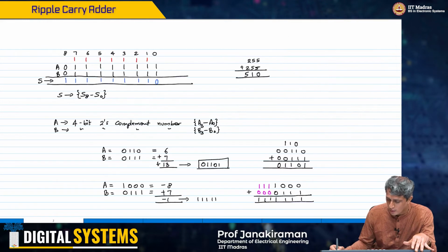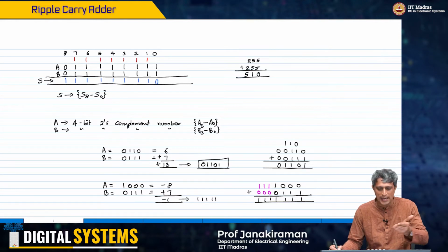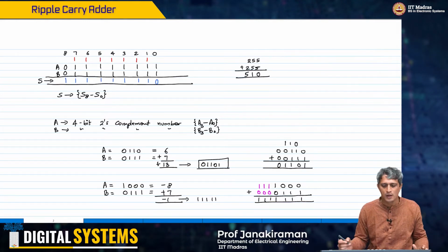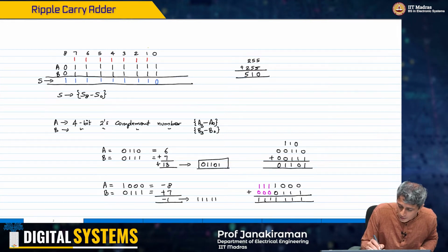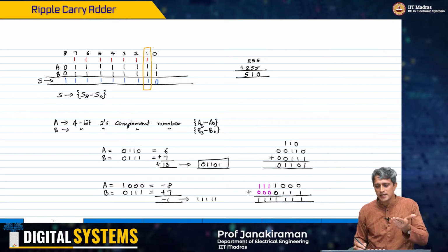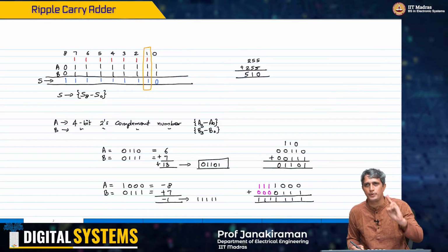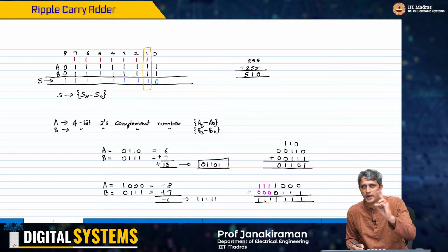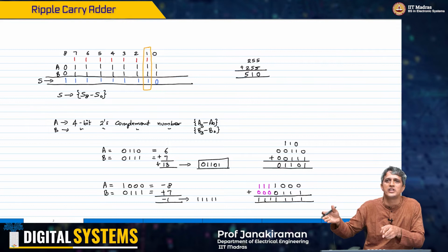If we go back and look at the carry propagation through the addition circuit, you look at a single bit position. It takes 3 inputs: bits AK, BK of the inputs A and B at the kth position, and a carry coming in from the previous circuit.